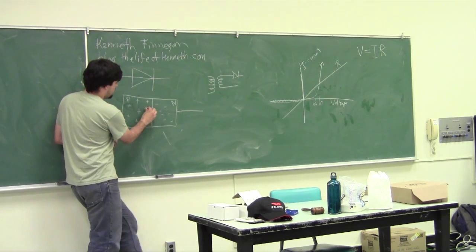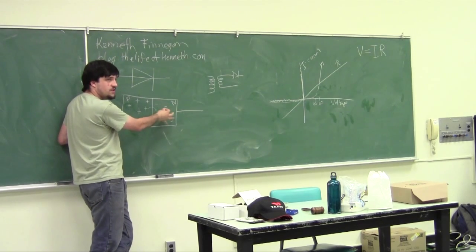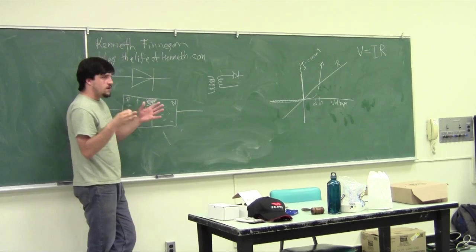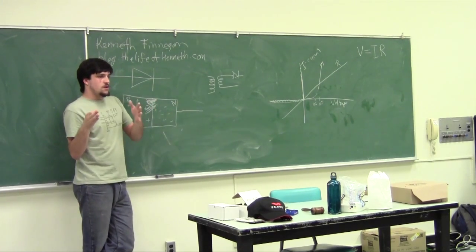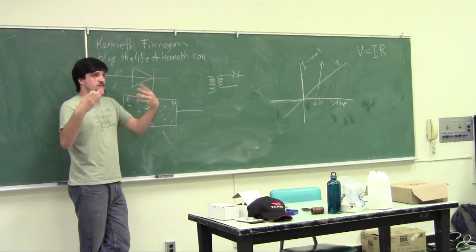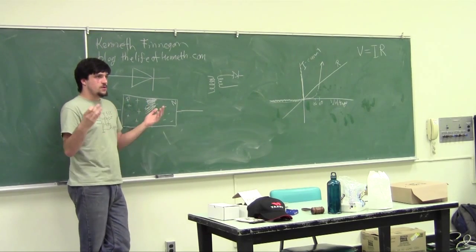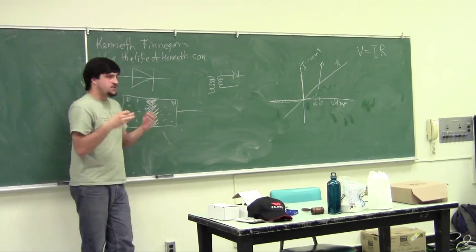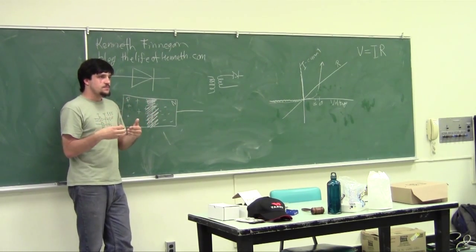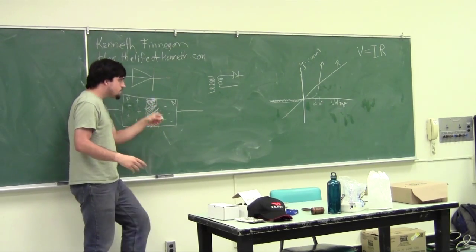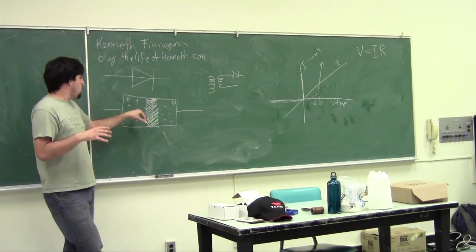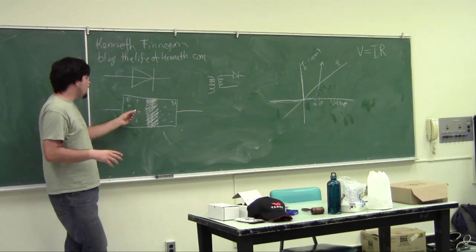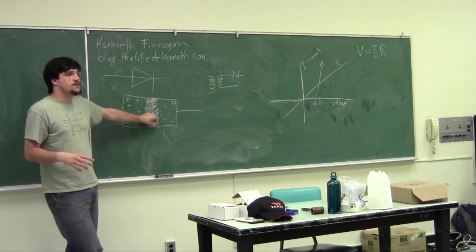And so what happens is positive charges start to migrate to the negative side and cancel each other out. But after they get canceled out and become a neutral semiconductor in that center region, the N and P semiconductors start to recreate their original charge. Luckily, this eventually reaches an equilibrium, and you end up with this section in the middle where the charges are created and cancel each other out at an equal rate. And so this is called the depletion region of the diode. So what this means is there's no positive charge and no negative charge in the center depletion region, and it's instead a non-conductive region. All right? This is why diodes do not conduct, right?